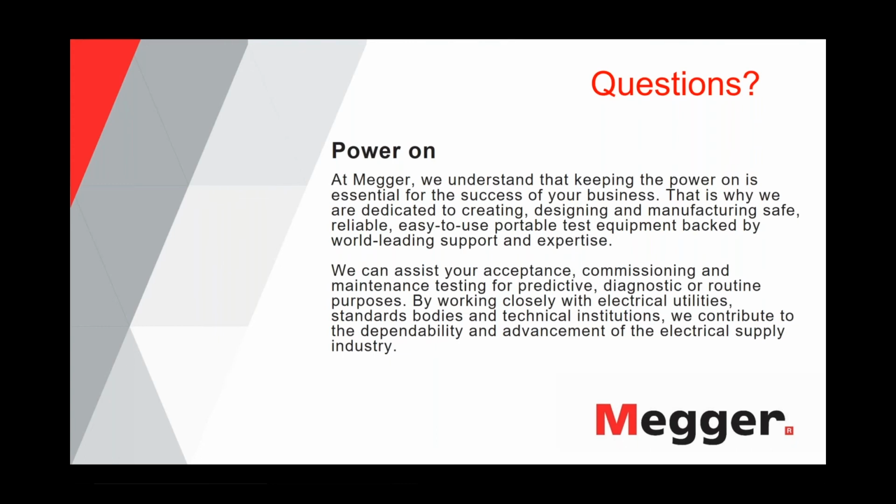Actually, to put a specific number on a result, because I guess this is what you're asking. You say, okay, I get these numbers. Will it fail in the next 3 years, or do I have 48 months or something like this? You cannot really do this, but you can know that your cable is in a non-critical condition, in a changing condition to the worse, or in a critical condition immediately.